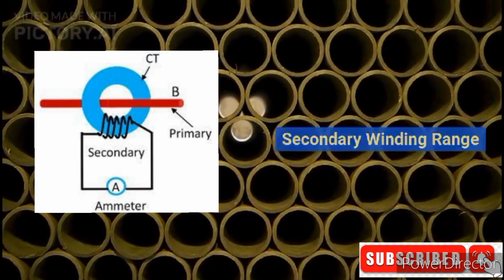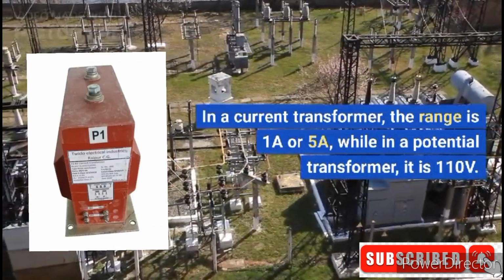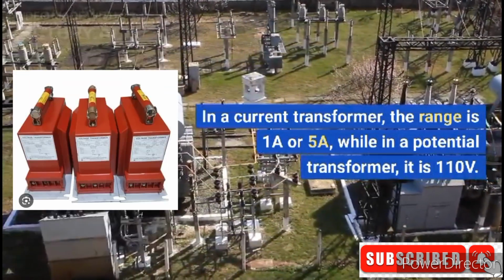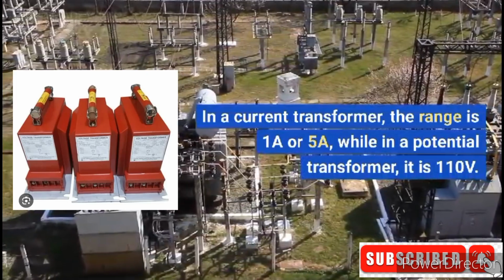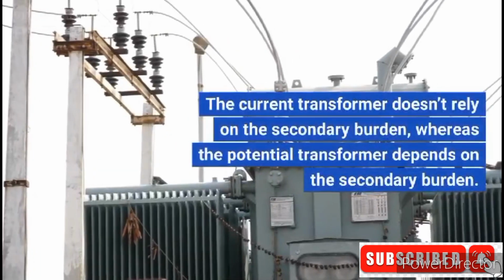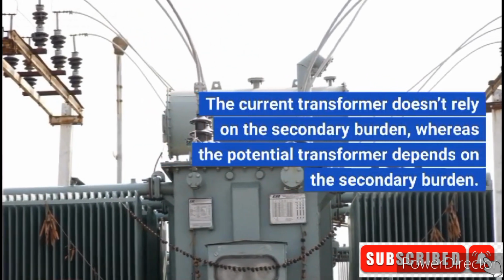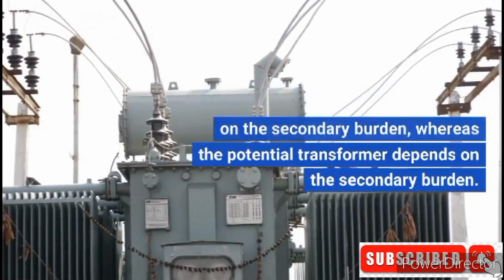Secondary winding range. In a current transformer, the range is 1A or 5A, while in a potential transformer, it is 110 volts. Burden. The current transformer doesn't rely on the secondary burden, whereas the potential transformer depends on the secondary burden.